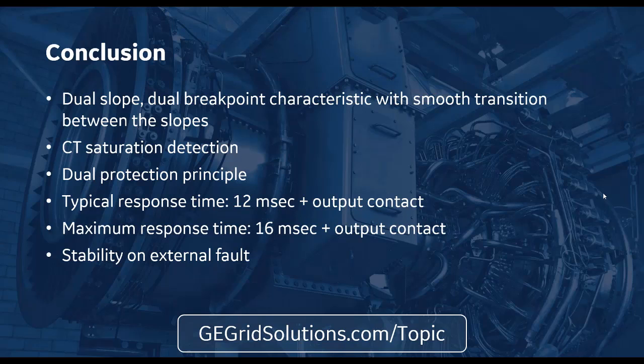Where you're going to run into this issue is if you go long runs, obviously longer runs, and you have low currents. But shielding issues come in not so much for the CT currents, but for the trip signal. Depending if you're running a trip signal to the breaker and it's a long distance, you could have capacitive discharge into that cable. And if it's not shielded properly, you could have discharge into that circuit and cause an operation of, whether it's a breaker failure initiate or an auto reclosing relay, because they're usually high impedance.